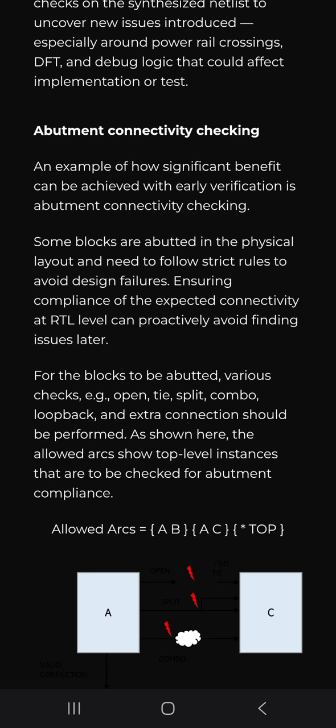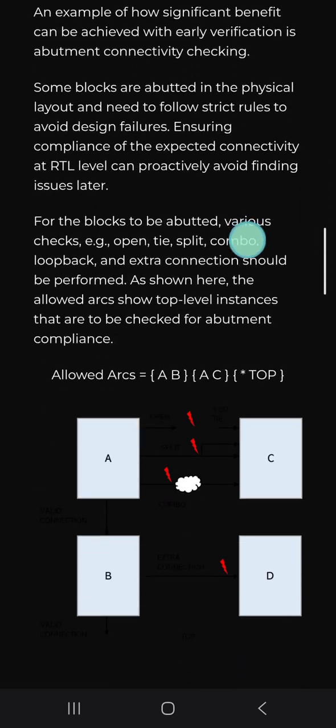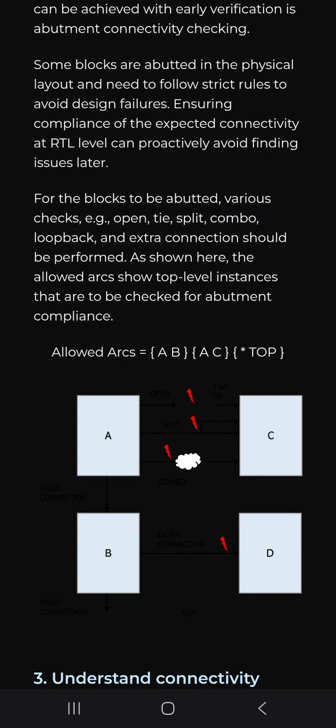For the blocks that are abutted, various checks, for example open, tie, split, combo, loopback, and extra connection, should be performed. As shown here, the allowed arcs show top-level instances that are being checked for abutment compliance. Allowed arcs.